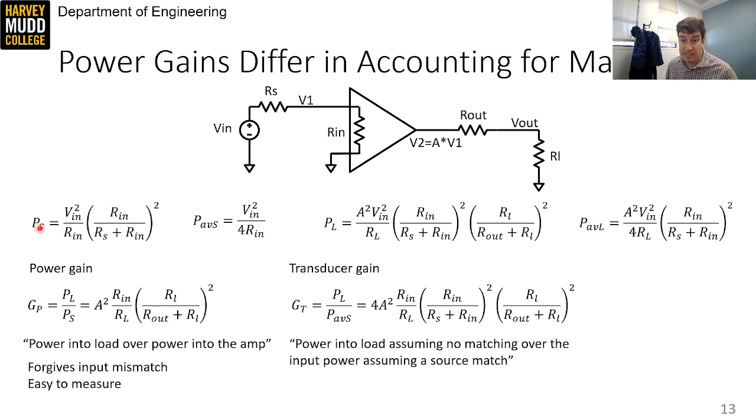So describing this gain in words, it's the power into the load assuming the input is source matched. Or you could say that it's the power in the load divided by the best possible power we could get from the source.